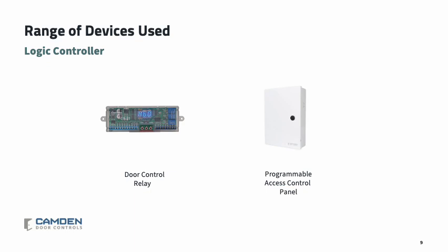I want to end this section by talking about the logic relay. Although it's possible to program an access control panel for privacy applications, a dedicated door relay controller has the advantages of low equipment cost and factory default programming. That factory default programming enables the installer to select the desired system operation from a list of menu options and complete the installation in just a few moments.